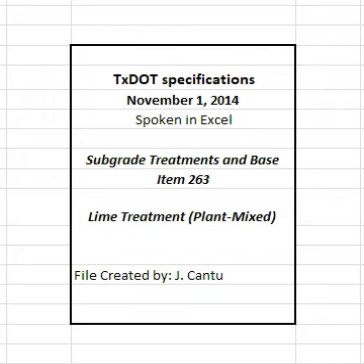4.4 Reworking a section. Rework the section, without adding additional lime, to provide the required density when a section is reworked within 72 hours after completion of compaction. Add additional lime at the rate of 25% of the percentage determined in section 263.2.5, mix design, when a section is reworked more than 72 hours after the completion of compaction. Reworking includes loosening, adding material or removing unacceptable material if necessary, road mixing as directed, compacting, and finishing.